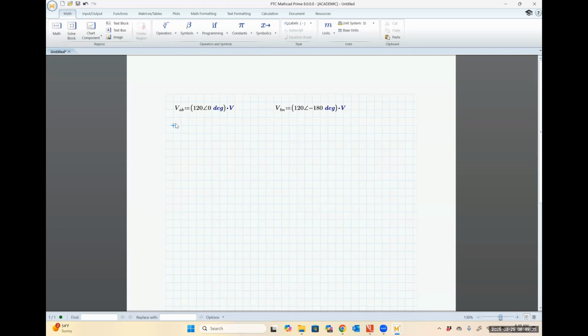So just to recap there, I get my subscripts by pressing Control minus. The angle operator is Control Shift P. Since there isn't a keyboard shortcut for a degree symbol, I just type the letters DEG. And I know this is going to seem weird, but I'm always going to explicitly multiply my unit times that complex number, because sometimes MathCAD can be fickle and it will treat stuff inside a parentheses as if it's a function when I don't want it to be. If I explicitly multiply by the unit, it never does that, so that's why I'm doing this.